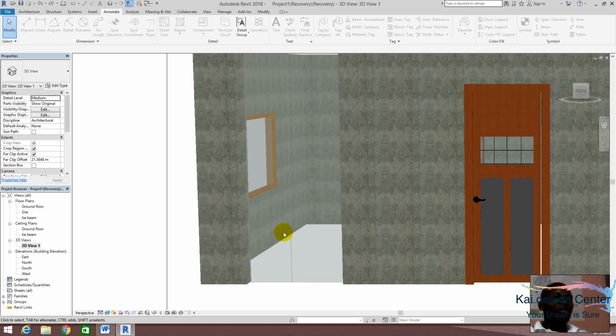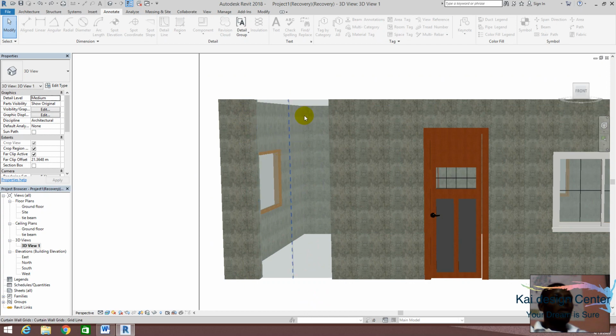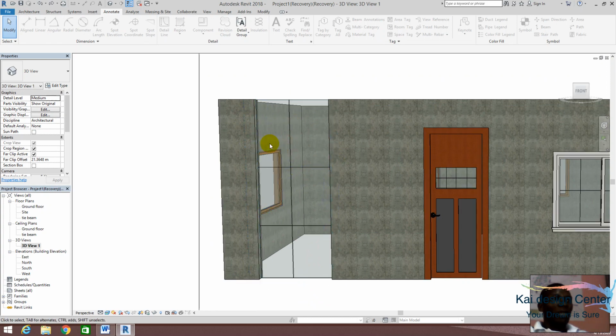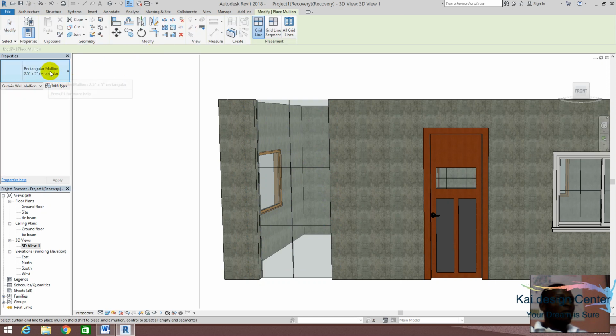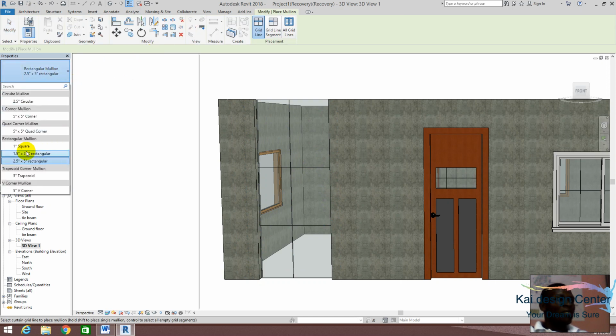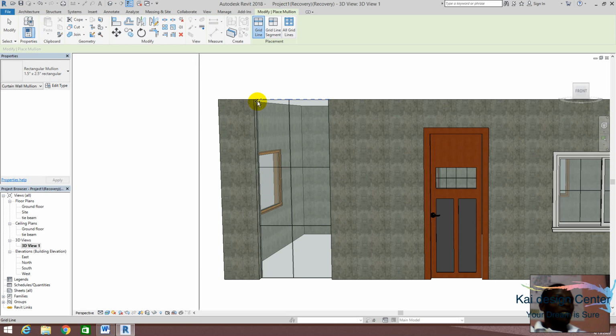Now you can create your cutting and whatsoever you want to create in here by going again to this and choosing the mullion. The mullions here are some smaller pieces. Maybe it can be frames of 2 by 2 centimeter, which is 20 millimeter.